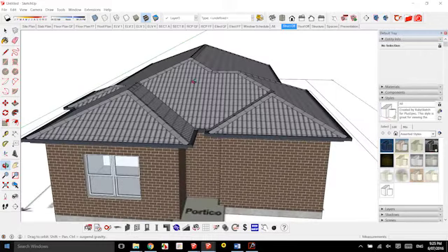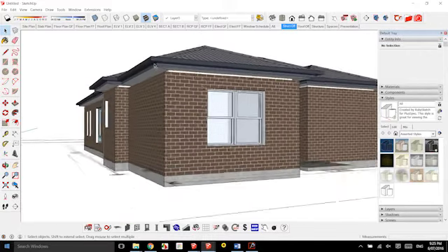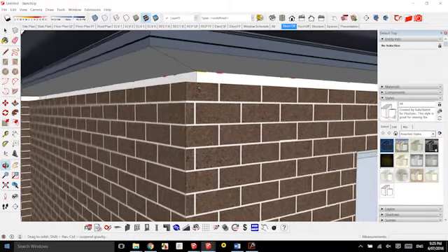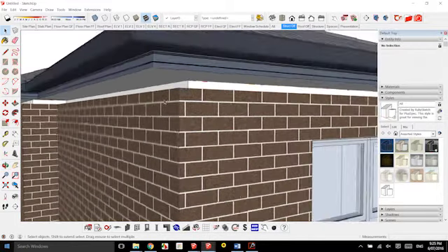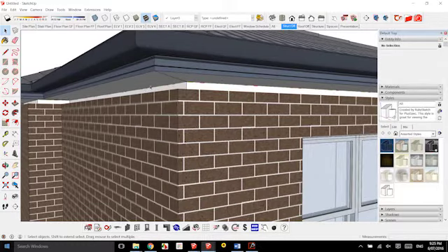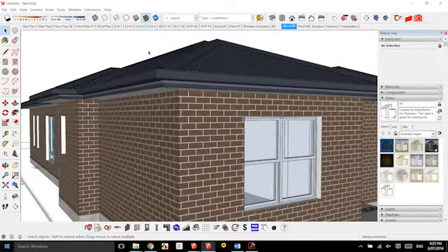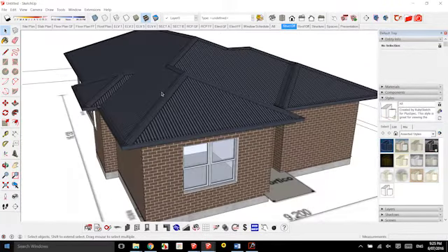Can you just show me what happened to the eave there? Notice that we had a drop off set on that wall before, and now I have a recess there and I can see my insulation. That is to save the cost of construction. No one actually puts the bricks up through the eaves unless the customer specifically requests it. Maybe just undo that roof and go back to the original drop off. So now it's gone back to the 600 drop off.